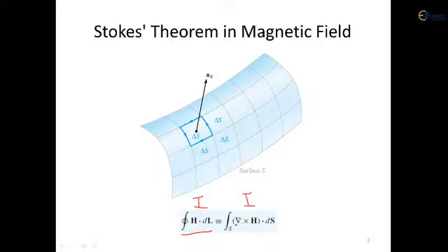As you see, del bar cross H bar here. With this del operator, which is a vector differential operator, the cross operation with a certain vector denotes its curl operation. The curl we have already learned so far. This is nothing but the rotation of a vector with respect to the area that it traces. So the rotation or circulation of the vector that you see here, for the magnetic field intensity, gives us capital J. Capital J is nothing but the cross sectional current density.